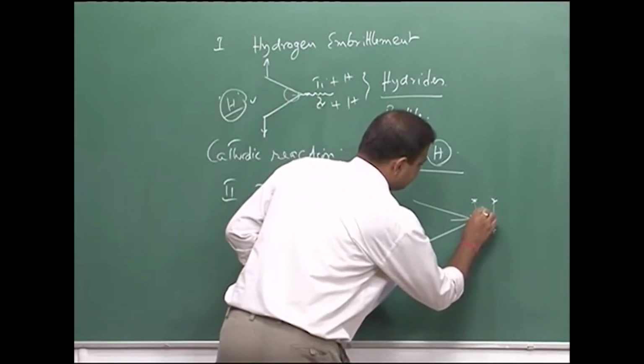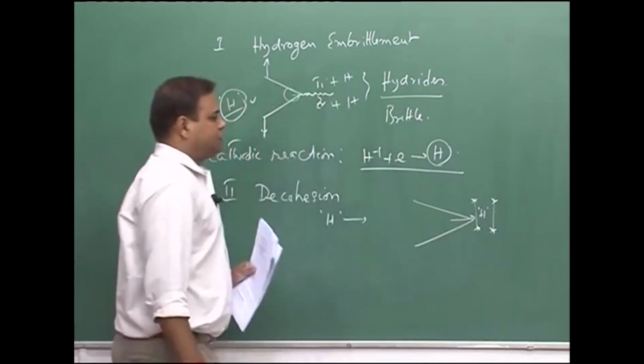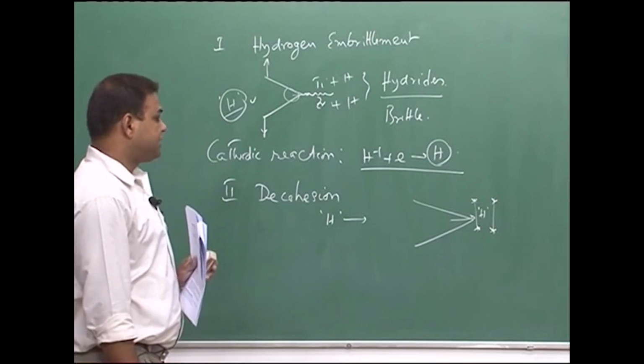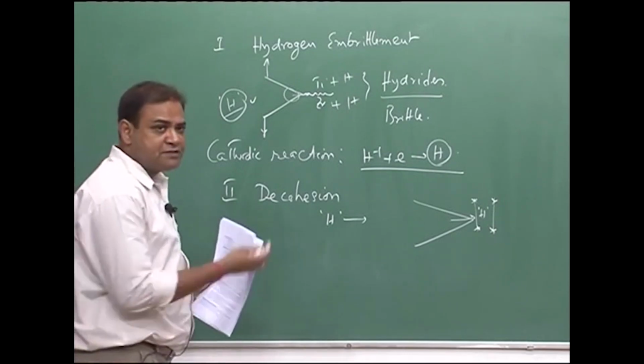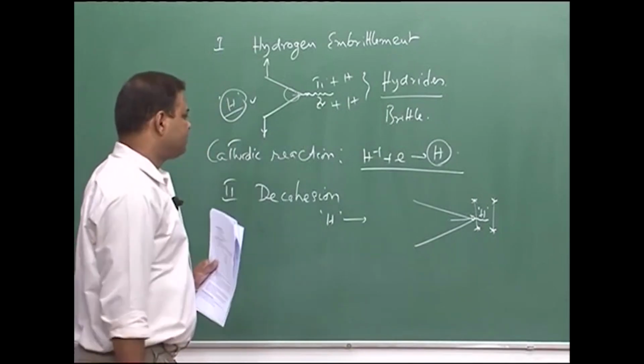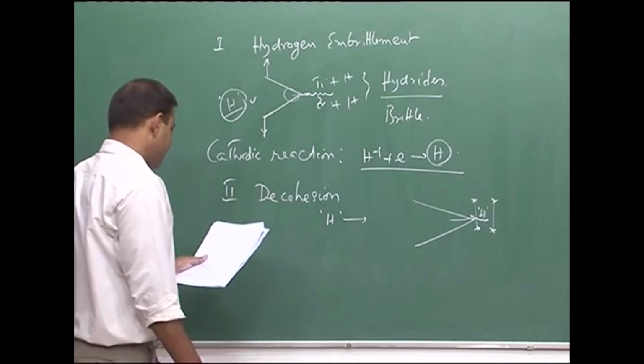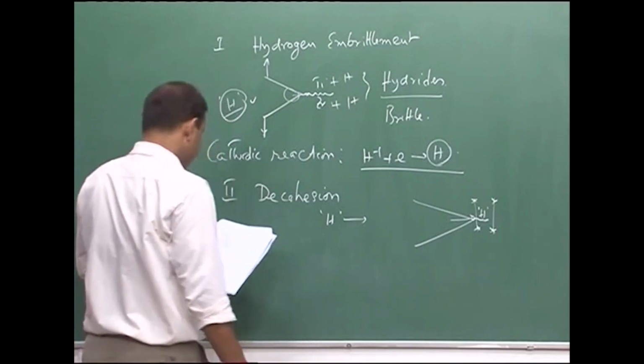Hydrogen can get in, and then it weakens this interatomic bond strength, and if it weakens, the crack can propagate, because at a lower stress value the crack growth can be possible. And here actually it reduces the surface energy.